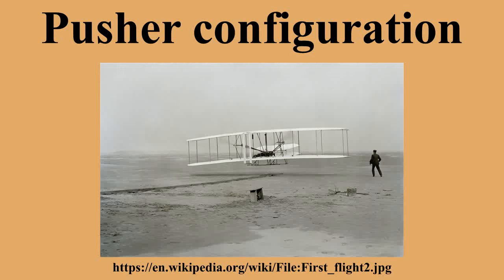Propeller efficiency and noise. The propeller passes through the fuselage wake, wing and other flight surface downwashes, moving asymmetrically through a disk of irregular airspeed. This reduces propeller efficiency and causes vibration-inducing structural propeller fatigue and noise.